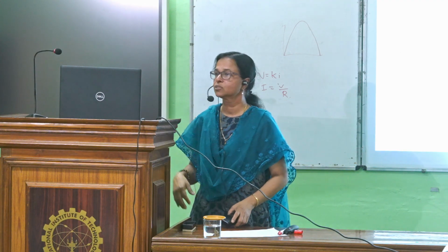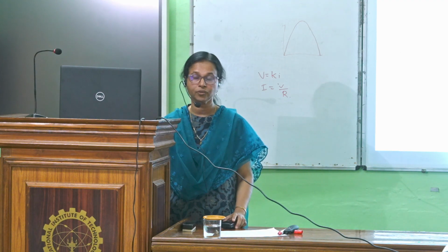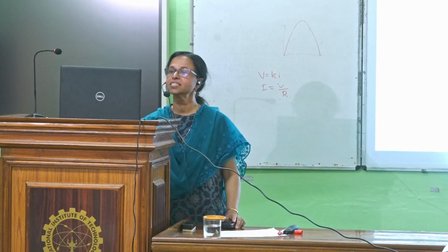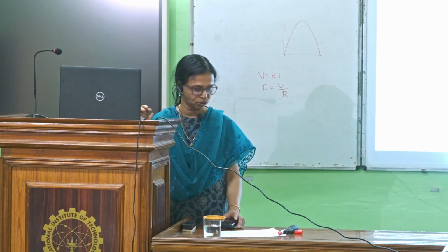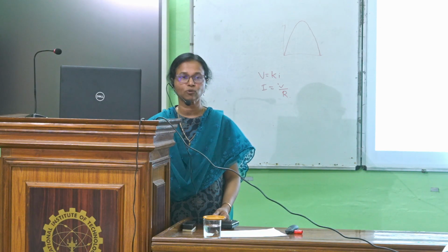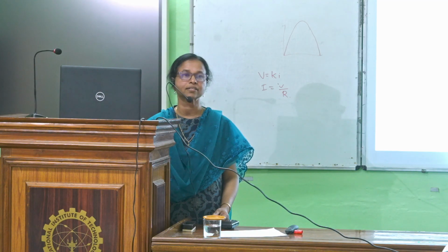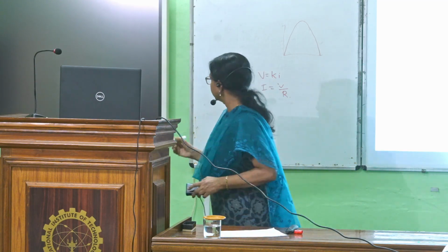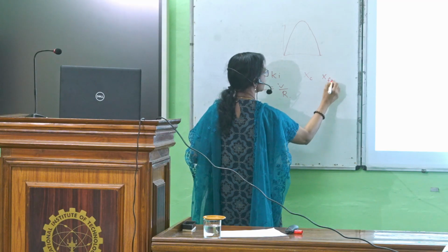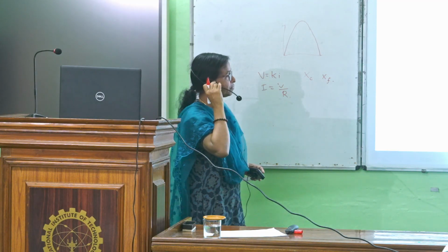Saint-Venant's equation. So the continuity equation is based on mass conservation, and the other is based on momentum conservation. Here, when you consider what XC and XF are, those who have already done hydraulic modeling using HEC-RAS, compared to the original Saint-Venant equation, what are those independent variables XC and XF in this equation?